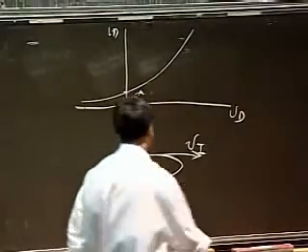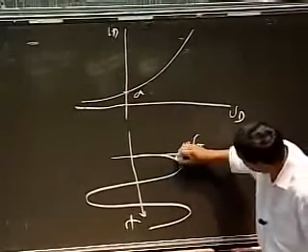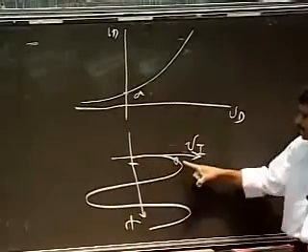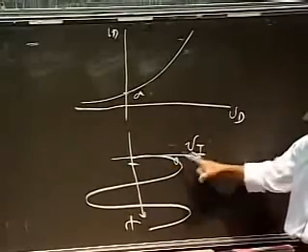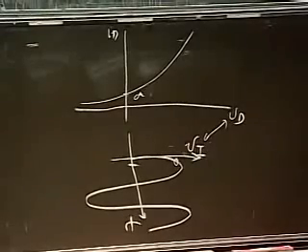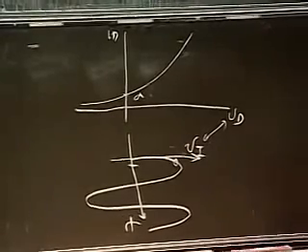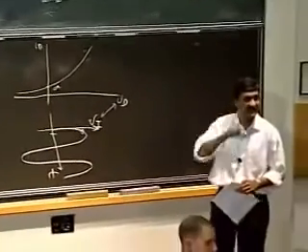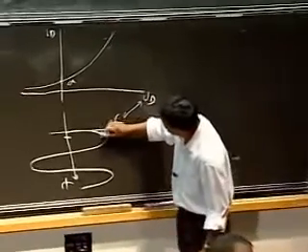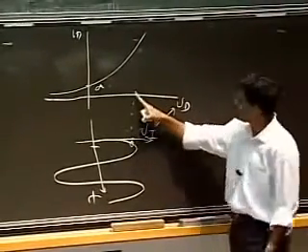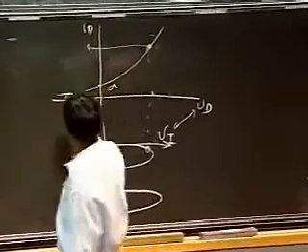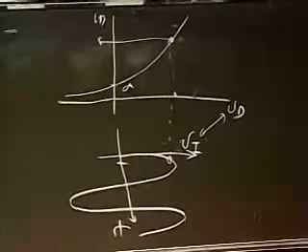So I can see where these points correspond to on that curve. Okay? So what this says is that at some point here, for example, when VI is here, notice VI and VD are the same thing, okay, because VI is applied across VD. Okay, VI directly applies across the device, and so VI equals VD at all time. So this voltage here corresponds to this voltage, which corresponds to this current, and then I can find out what the current is for that voltage.